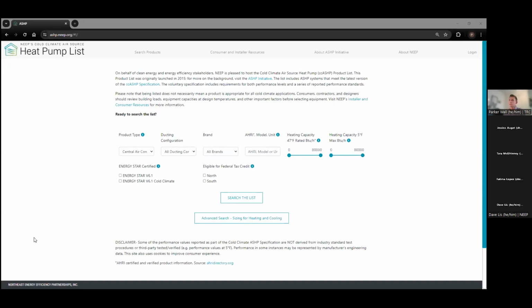And reshare my internet. So this is the NEEP tool, the NEEP cold climate air source heat pump list, advanced sizing for cold climate air source heat pumps tool. This is the homepage. So if you type in this URL right here, ashp.neep.org, we'll land on this page. It'll ask you who you are, and then you'll have the choice of all these inputs that'll help you size your system. So you can go through product type, ducting configuration, brand, HSPF, heating capacity at 47 and 5.